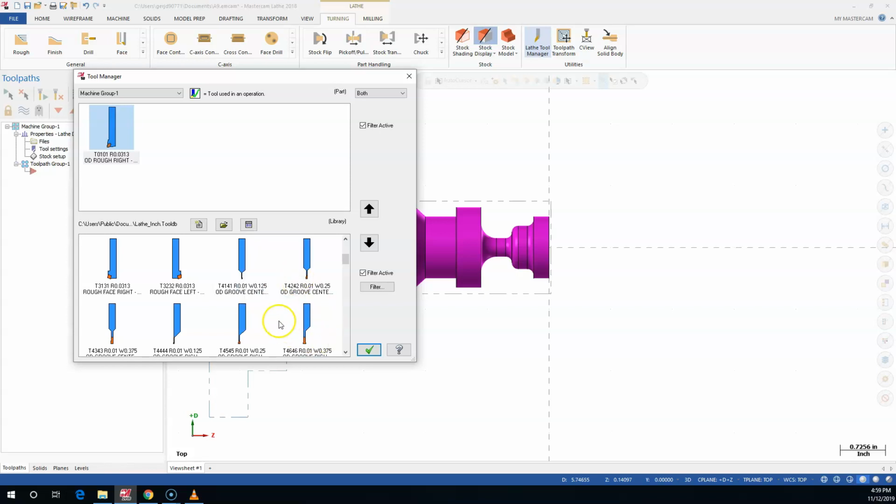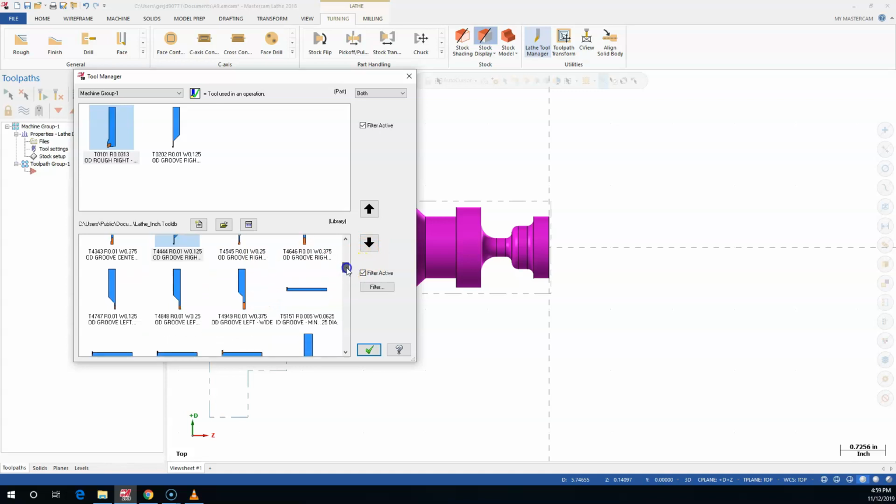So let's go right to a grooving tool. Center, left, left, right, doesn't really matter. I would say I tend towards the right side just because we're coming up against that spinning chuck, and I guess that's typically the one I'm going to pick. So I picked an 1/8 inch. We could go up to whatever this width is, but at some point we're going to have trouble calculating the tangency. So most shops are going to have those 1/8 inch insert cutters, so we can go with it.